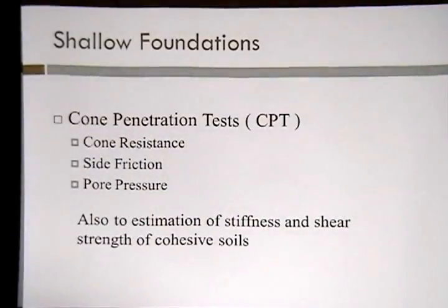Cone penetration tests are conducted to obtain the cone resistance, the side friction, and the pore pressure. The soil type can be determined by analyzing these results. The values can also be used to design the shallow foundations through the estimation of stiffness and shear strength of cohesive soil.